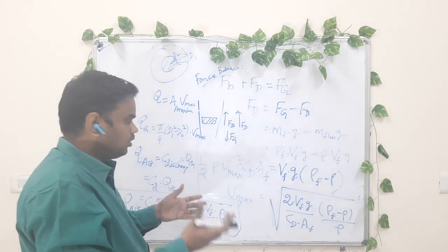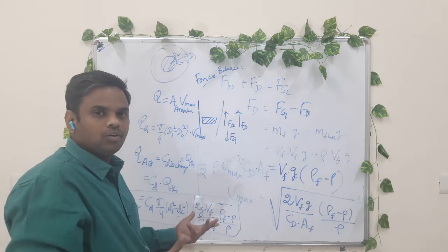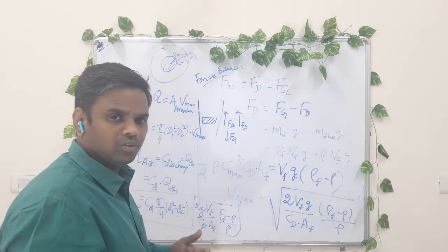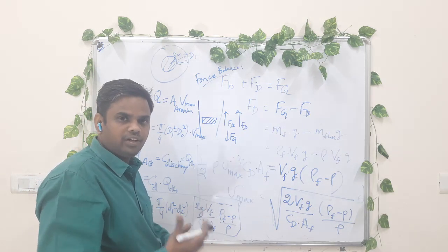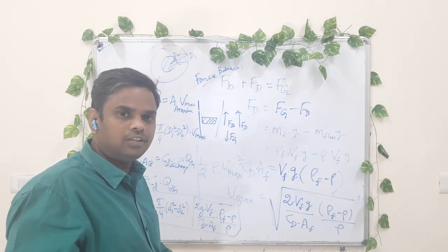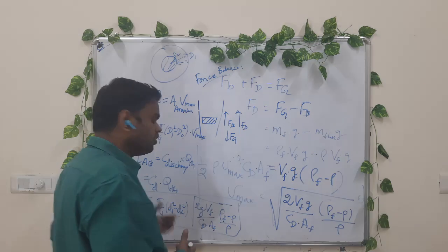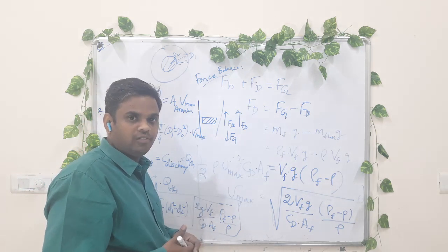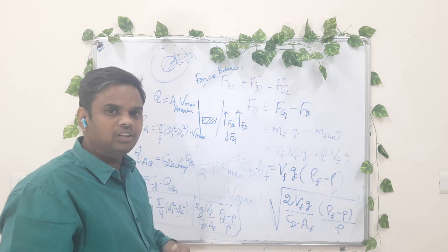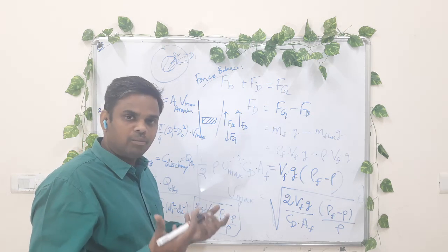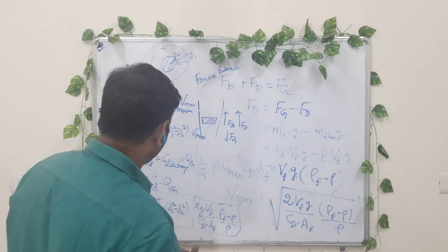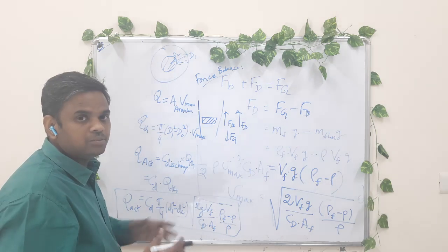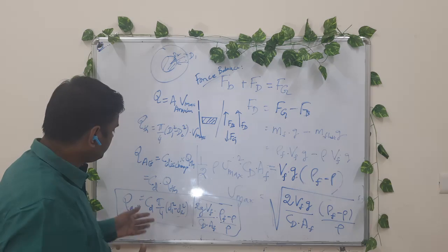It's again similar to an orifice, so it has a better coefficient of discharge than the orifice. For orifice meters we have a very low coefficient of discharge, less than 0.6. So for the rotameter it is going to be more than 0.7. For venturi meters, it is possible to get, with a very well calibrated or new venturi meter, even a 0.9 coefficient of discharge. So the Cd of a rotameter lies between the orifice meter and the venturi meter.